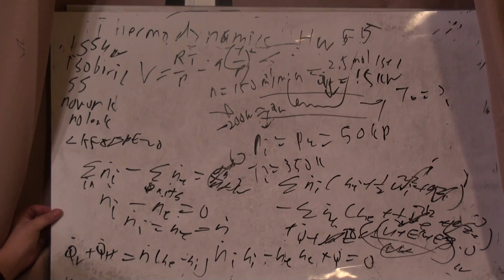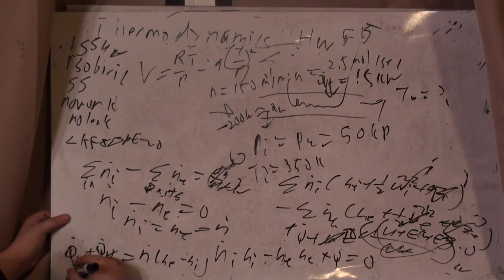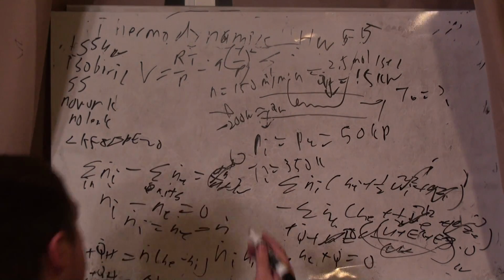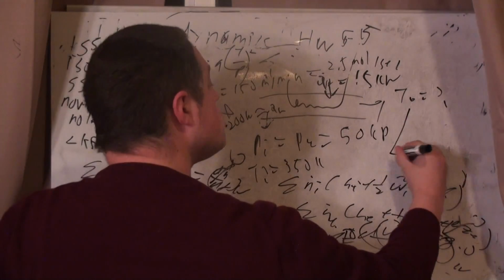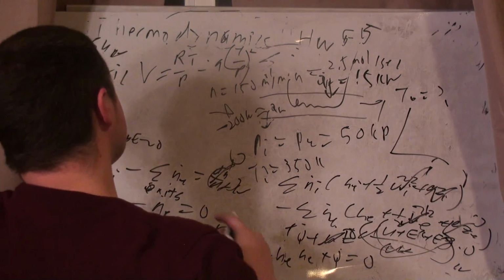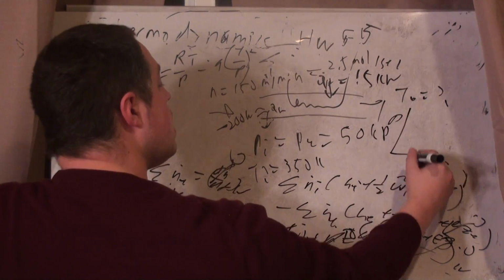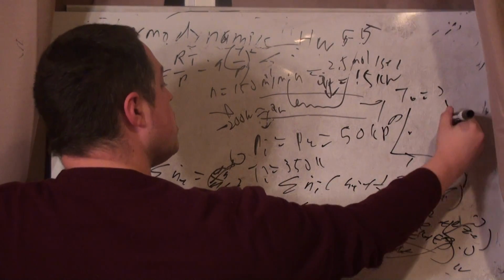And I want to find a temperature. And so I'm going to have my q dot L plus q dot H divided by my molar flow rate is equal to my delta H, which, because this is a real system, I need a departure function. So I'm going to draw a departure function thing. Well, I have V as a function of T and P, so I'm going to have P and T, and so I'm going to go from here to here.